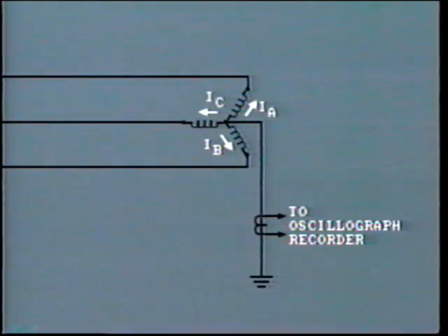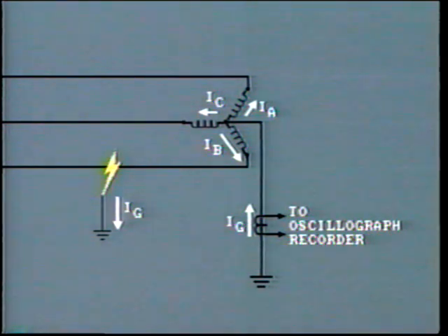Remember, the magnitude of current for a single line-to-ground fault is just 3 times its zero-sequence component. Another very sure way of detecting ground faults is to monitor the current in the grounded neutral of a Y-connected transformer winding. Again, this current is quite small under normal, balanced conditions, but rises significantly when a ground fault occurs.